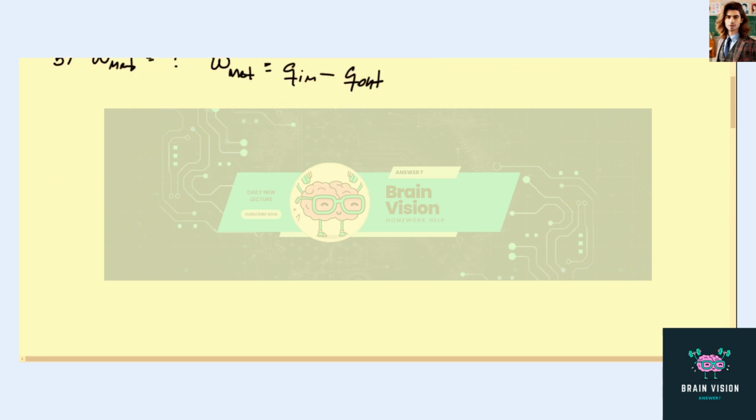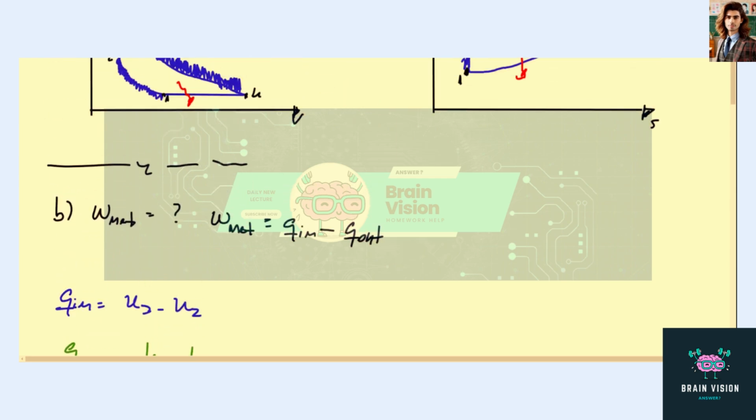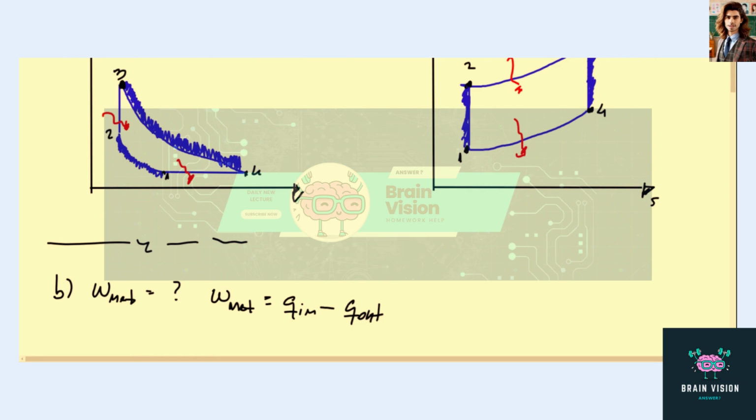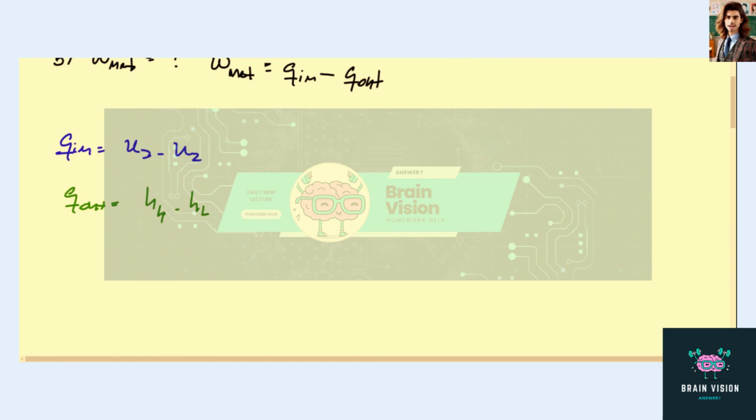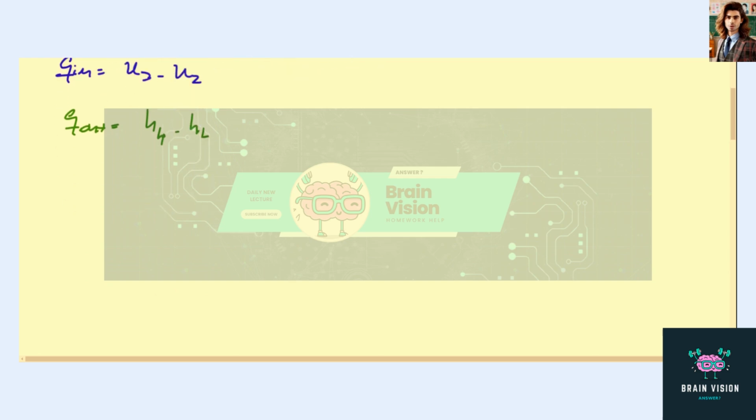We just need to know that the input heat is going to be the change in the internal energy, so it's just U3 minus U2, and the output heat is going to be the change in the enthalpy. That's because the output heat, which is the second red arrow here, is a constant pressure transformation, and a constant pressure transformation means the energy is the enthalpy. Therefore, we need to find the internal energy in points 3 and 2, and the enthalpy in points 4 and 1. So let's begin with point 1.